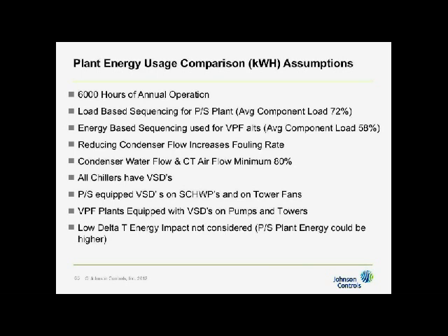For a VPF, we're going to assume energy-based sequencing, and when you use energy-based sequencing or a CPO type of control, the average component load drops. In this case, it ended at 58%. We reduced our condenser water flow, but we also know that when you reduce condenser water flow, you're going to get an increase in your fouling rate. We took that into account.